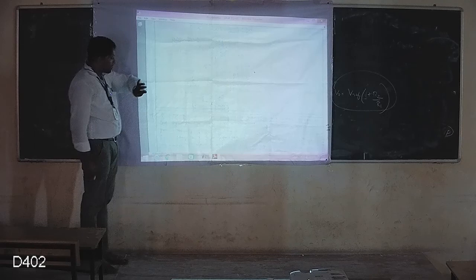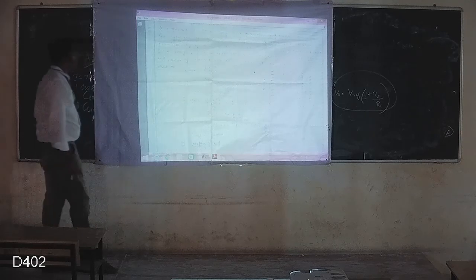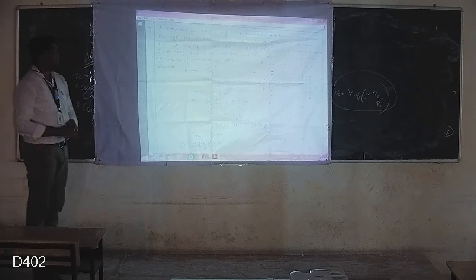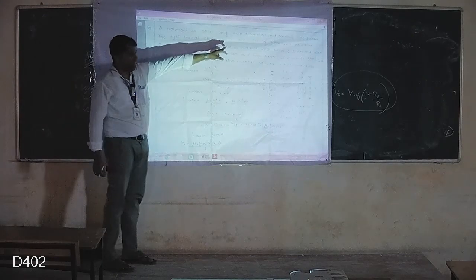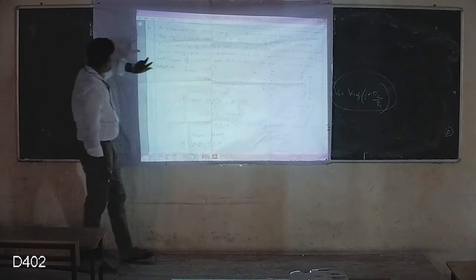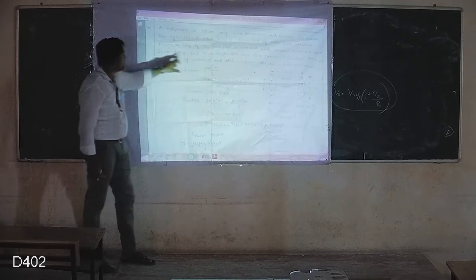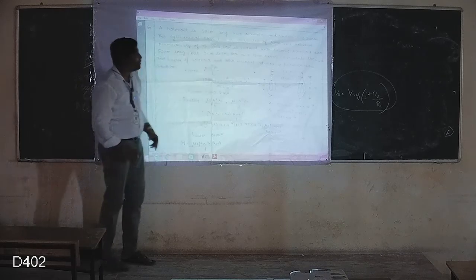The last problem of this session: a solenoid is defined as 50 centimeter long, 2 centimeter diameter, and contains 1500 turns. A cylindrical core has a diameter of 2 centimeter and relative permeability of 75. This coil is coaxial with a second solenoid, 50 centimeter long but 3 centimeter diameter, with 1200 turns.